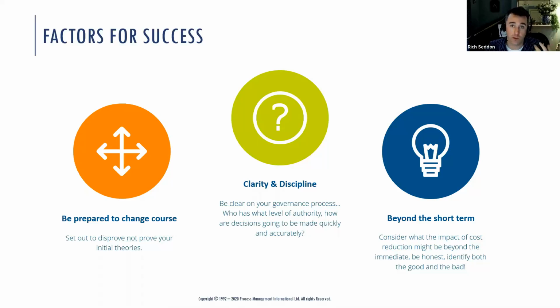He had a theory, and he willingly set out to disprove his own theory. So in this circumstance, we ran a test. We put PDSA, Plan, Do, Study, Act, into action and bought a small quantity, a safe experiment, of this material to run on a few machines for a week to see what happened and how they performed. We monitored, established how we'd know a change was an improvement or a deterioration for that matter, monitoring things like waste to recycling, machine uptime, and similar kinds of measures. And on all counts, the experiment failed.